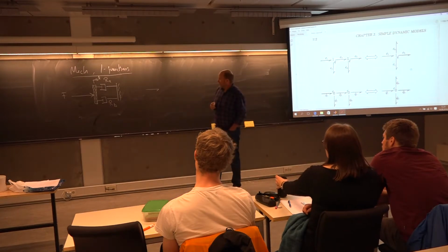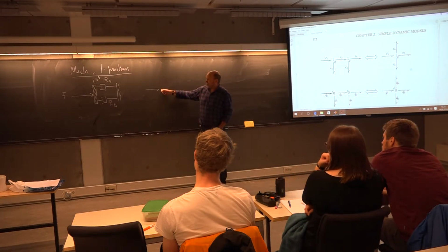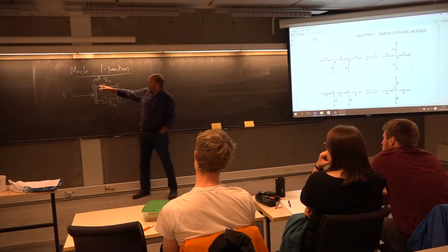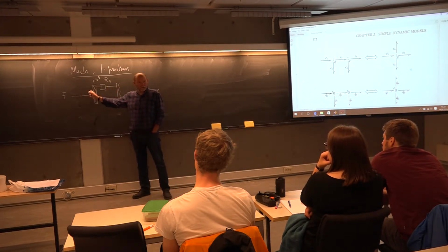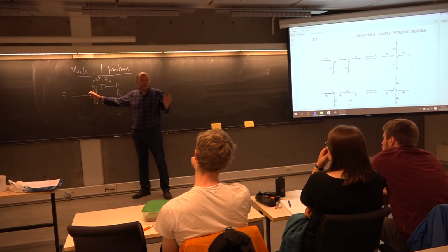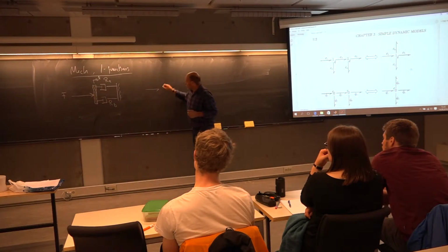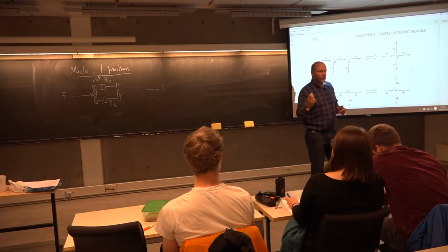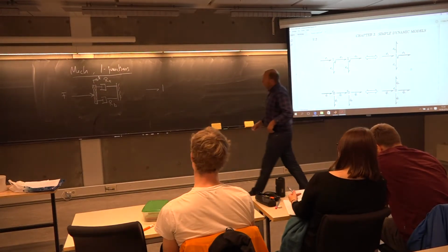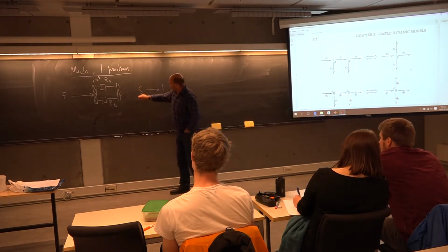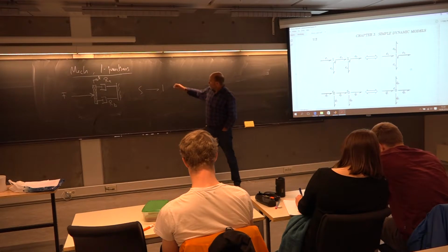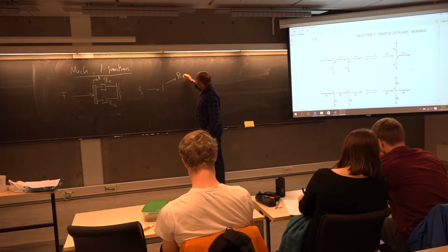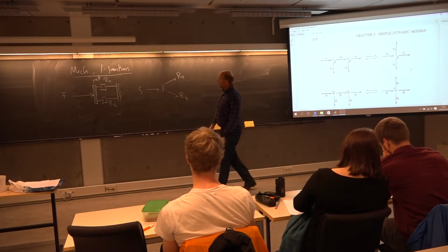Well, what kind of junction is this? For all these connections, all these different elements connected to it will have the same motion, the same velocity. Hence, this is going to be a one junction. They have the common flow, the common motion. So here I will have a force acting, that will be a source, and then it will split, hitting one resistance and another resistance here.